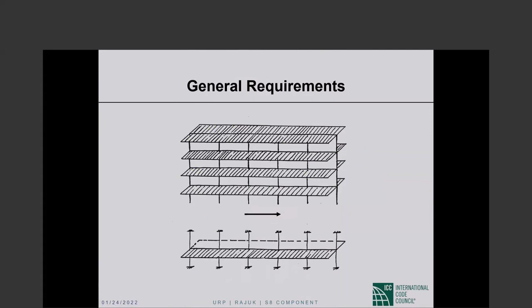But when we are treating gravity loads, when we are considering our slab subject to gravity only, then we can reduce this subsystem further down to what you see at the bottom. We can take a slab strip on any particular level as shown in the picture, and then we can take the columns that are directly supporting the slab strip.